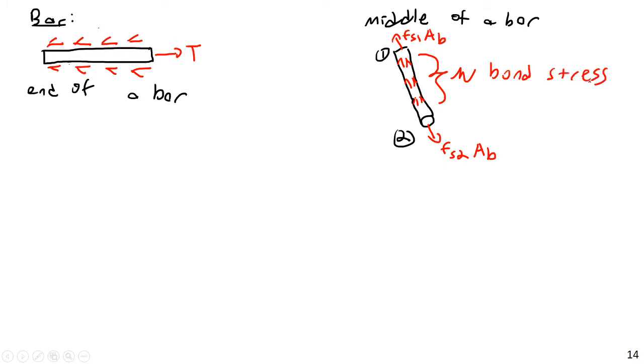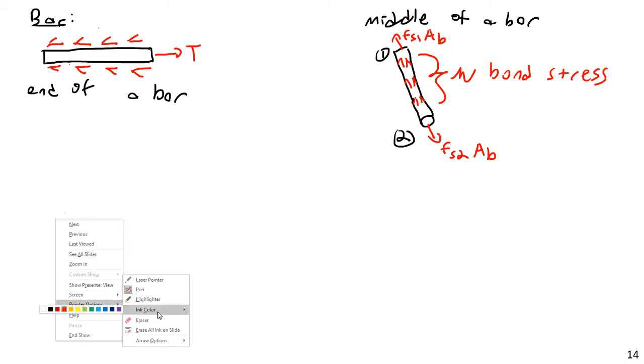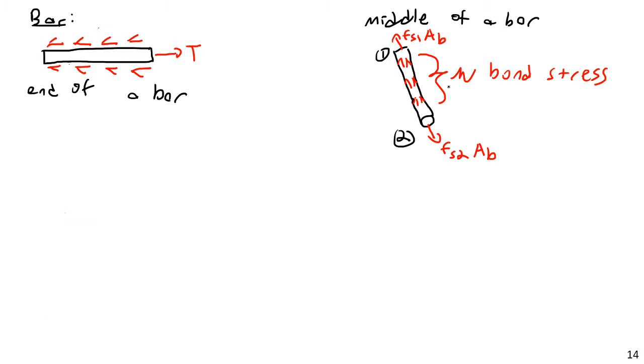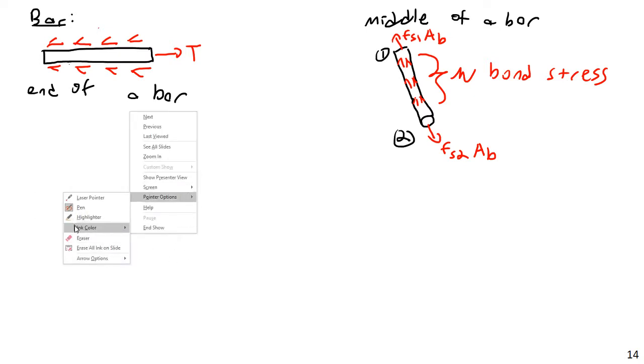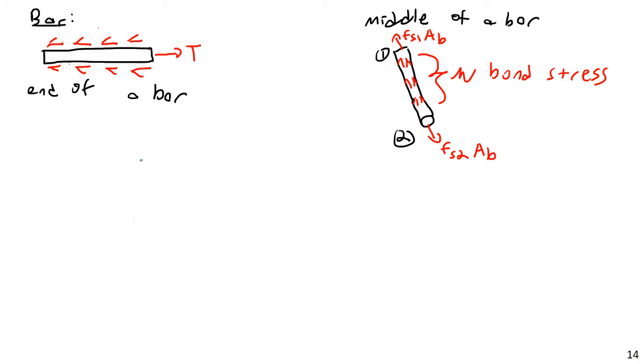The bond stress. And so let's apply some equilibrium equations. I want to apply equilibrium to this. There's some bond stress mu applied, or some average bond stress mu applied over the cylinder here. Then I have a stress on one end, a stress on the other end, multiplied by the appropriate bar area. So let's apply equilibrium to this bar here.